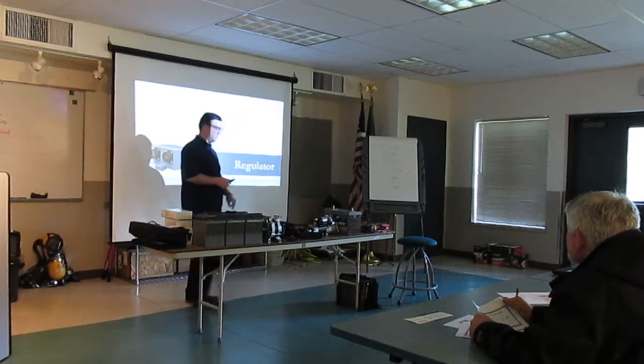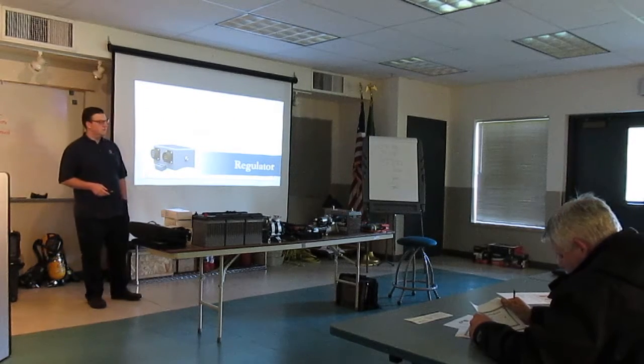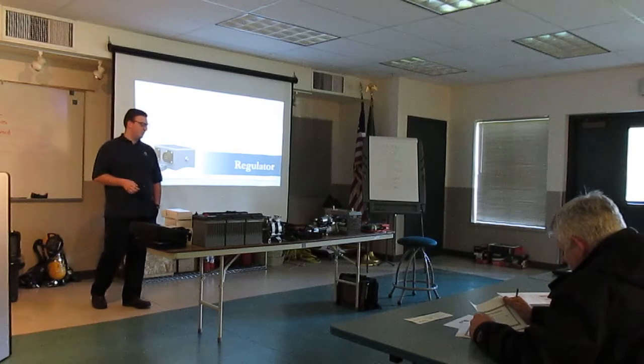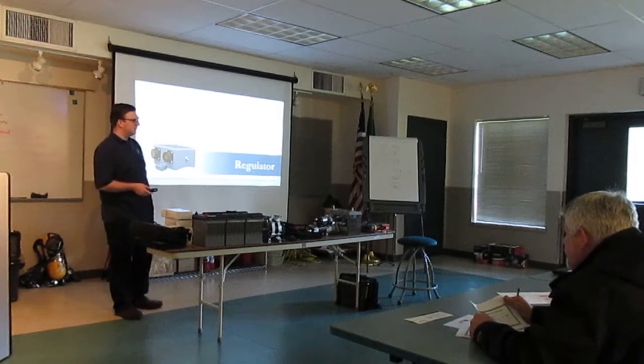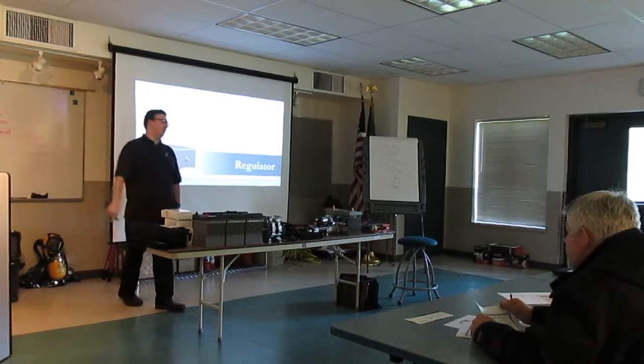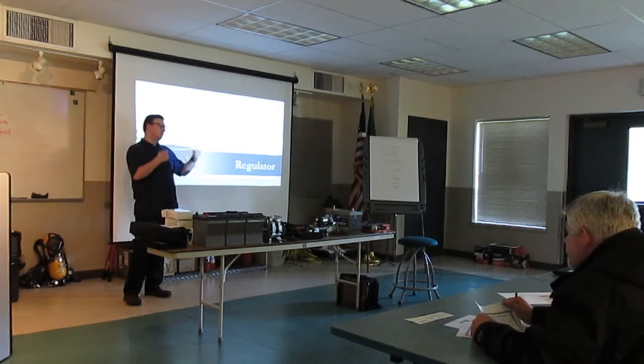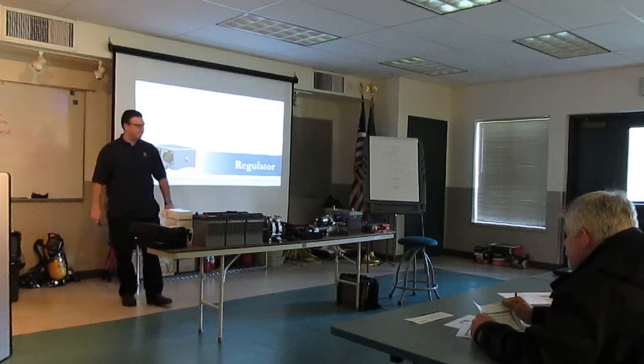You have the 700s. The 700 series, yeah. That's a flat 5-pin, except for the newer 714, I think it's got the round 6-pin. We have adapters that will let you switch from the older style. So you can keep the old alternator on, just switch the regulator and just plug it in. And a harness, you get the harness.